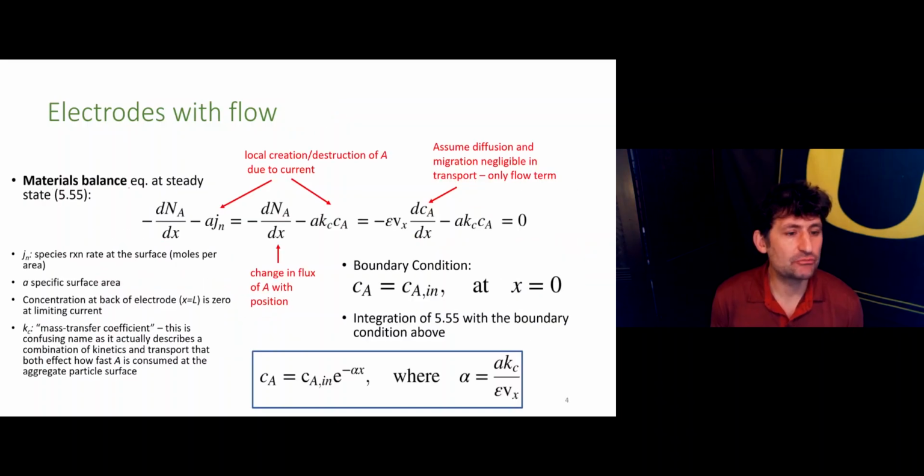Next, we're going to write a materials balance equation at steady state and solve that to find the concentration profile. At steady state, we can write that the time derivative, d/dt, of the concentration of A in the pores has to be equal to 0.